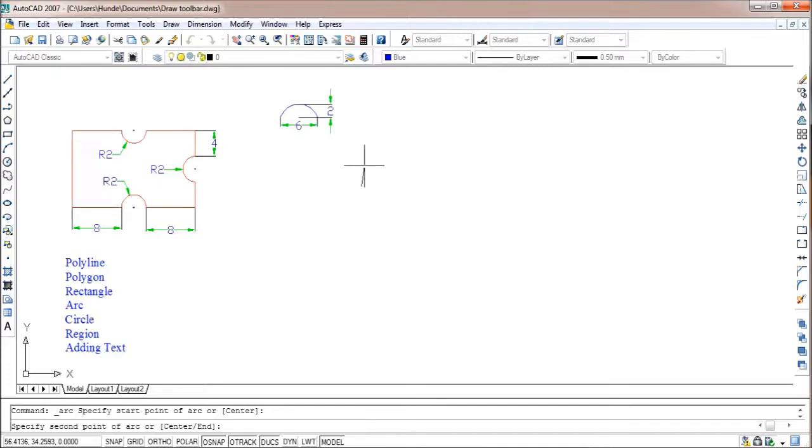We use the relative coordinate system since it is very simple to identify the pointers on the screen. The second point must be the midpoint. So we divide the opening of the arc, which is 6, by 2. That means the value of x will be 3. The value of y is the depth of the arc, which is 2.